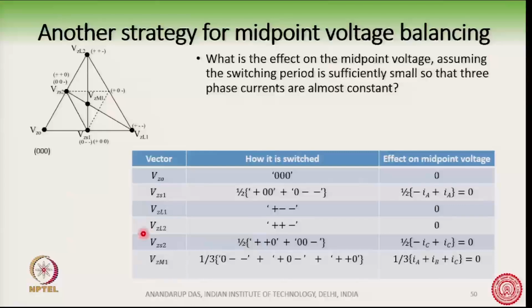The concept of this virtual space vector highly simplifies this problem, and it almost solves the problem. Also, as compared to the first technique that we discussed, this technique can be applied at any modulation index, because now the whole space vector diagram has been redefined, and so this will be applicable for any modulation index.